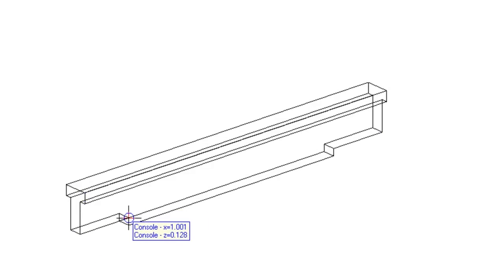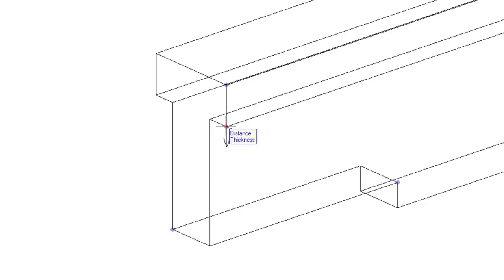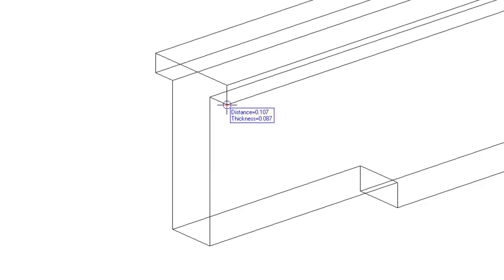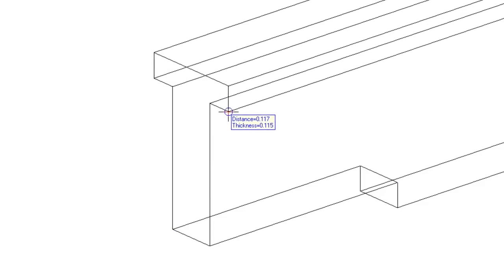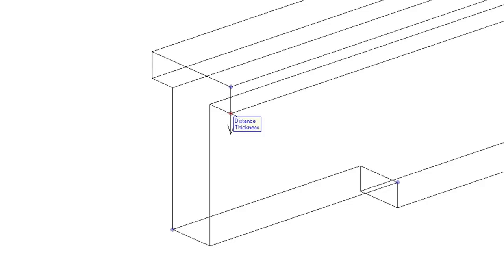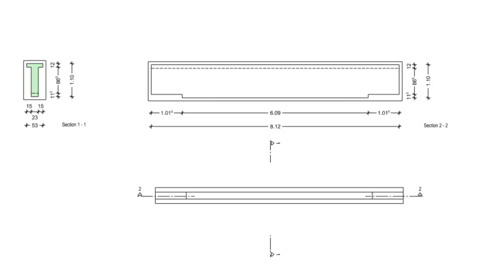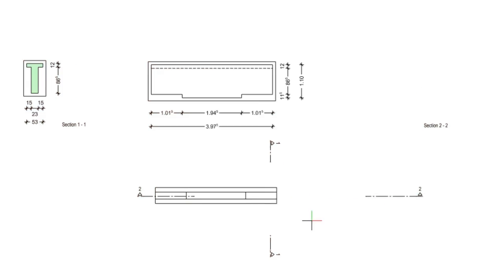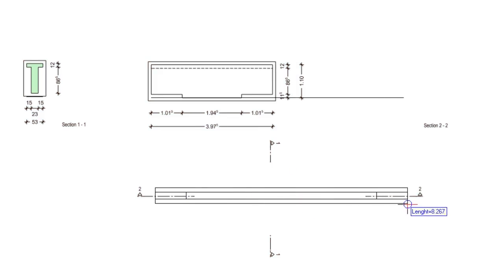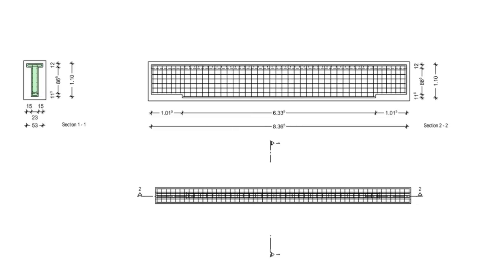Using parametrics, you can adapt the shape of the T cross-section to the beam. The values are checked visually without interruption by command sequences or sub-dialogues. This saves time when working and lets you concentrate on other important issues. Once the shape of an element has been determined, you can then create associative views and sections in the usual way. Of course, changes will also be made to these, so they can serve, for example, as a basis for the subsequent placement of the reinforcement.